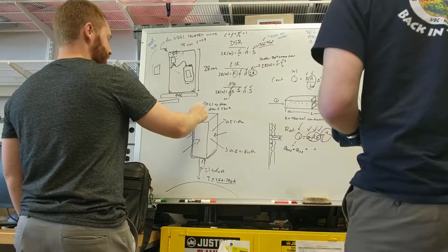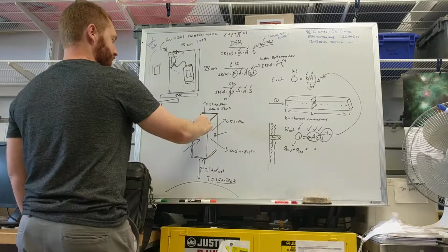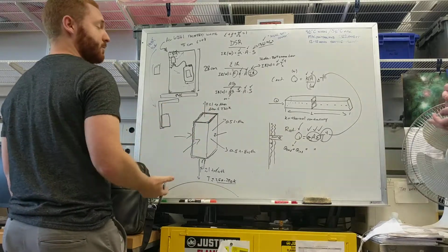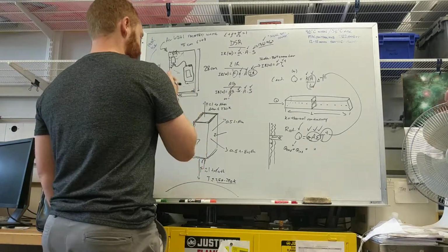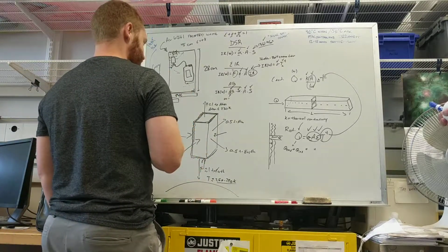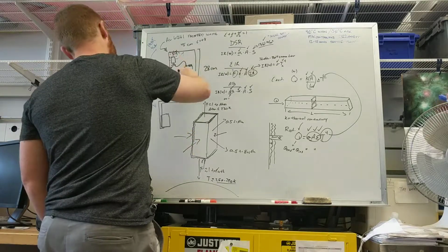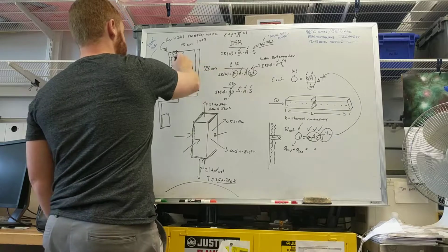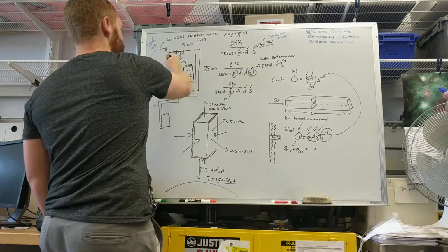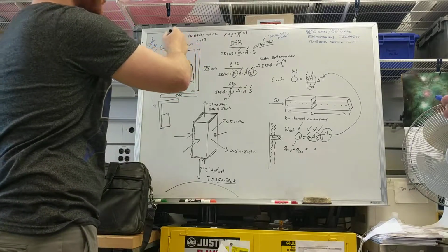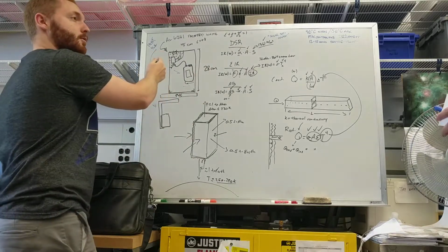So this is by far the most ideal surface for a radiator because you're dealing with by far the lowest environmental loading, radiation-wise. Okay, so if you wanted to figure out, given you wrap all 5 sides with MLI and then you have an aluminum bar that comes up that you bolt to your thing that's dissipating heat, you can bolt it directly to the top surface. Yeah. You can compute what the temperature of your electronics are going to be.